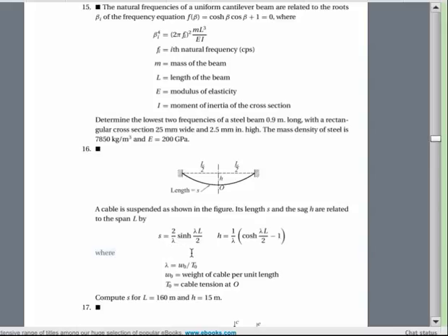So this uses the hyperbolic sine to describe the length of the cable, and the sag also involves the hyperbolic cosine. And these other parameters that are needed in terms of the angle involve this omega, or W0 divided by T0, the weight of the cable per unit length. So it takes into account the weight of the cable and the tension, what the tension value is going to be at this lower point, or the critical point there, 0, at the bottom of the sag.